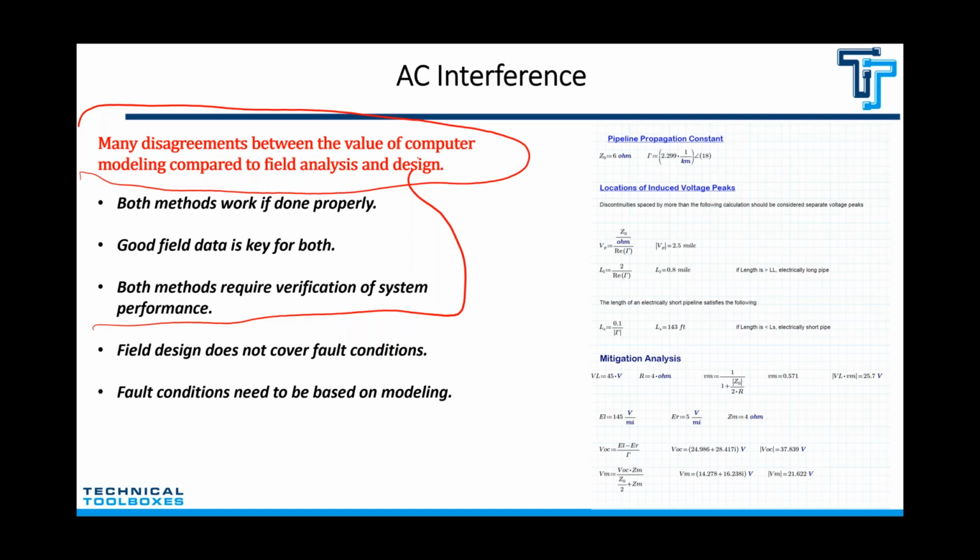You have to put data loggers out there and collect data over a period of time. I recommend you collect it for anywhere from a week to a month, to make sure you get the right data. But if you collect that data over a period of time, then you can use that. You can't just go measure it and do it based off that. If you go to that, you need to model.